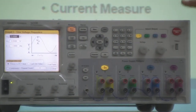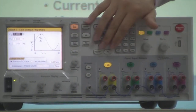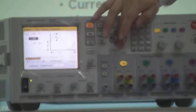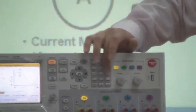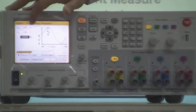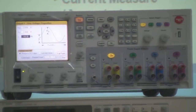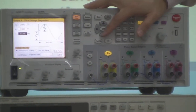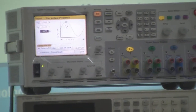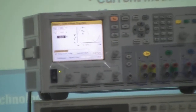When you select the sine wave, the waveform shows up, and you can look at the different parameters. We'll do 2 volts, and let's do 100 hertz. So you can select the voltage level, the amplitude, and also the different frequencies. The maximum frequency for this basic module is, I want to say, 500 hertz to 1 kilohertz.